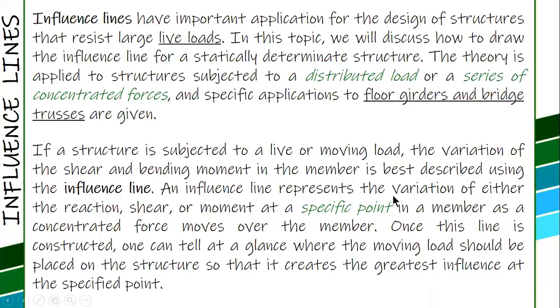So, once this line is constructed, one can tell at a glance where the moving load should be placed on the structure so that it creates the greatest influence at the specified point. So, it's like a visual aid, right? You can see where you want to put the unit load so that you will get the maximum value.